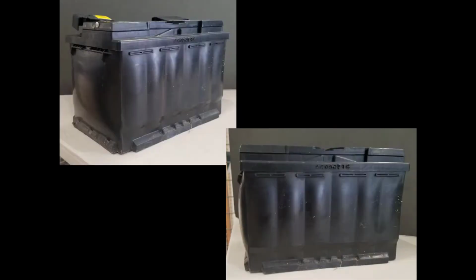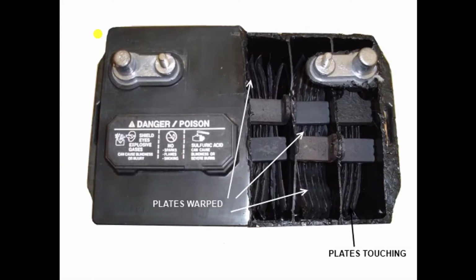Whenever we see swollen batteries, we want to definitely be extremely vigilant. Here's an example of a swollen battery, and you can see the case is swelling at each individual cell. This is extremely dangerous, and there are vent plugs too. This could have been a battery that wasn't allowed to vent, causing it to swell in this manner. When you see that, that needs to be replaced, period. There's no saving that. If you did have a frozen battery and you were able to thaw it, the plates themselves will become warped inside, and they could actually be touching, and they can actually short out a cell, and that's not good. So anytime a battery is frozen and it's confirmed frozen, you actually witness the swelling, it needs to be replaced.